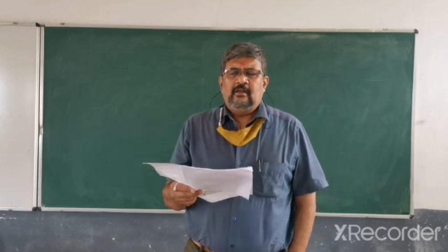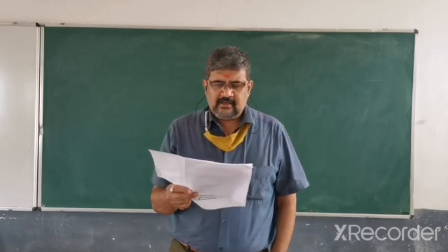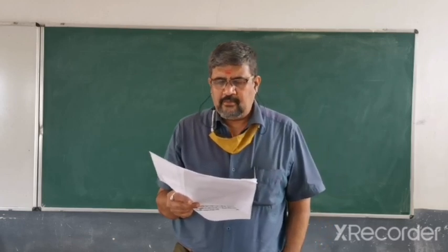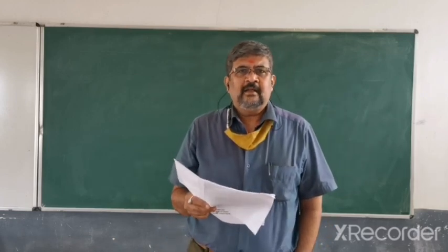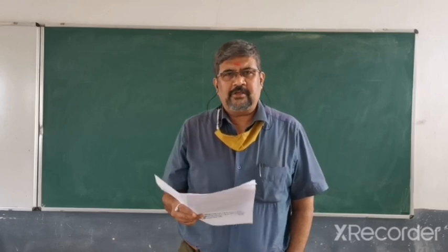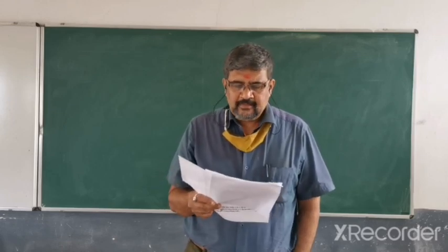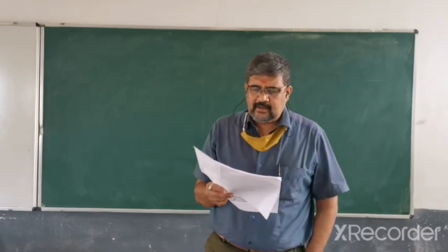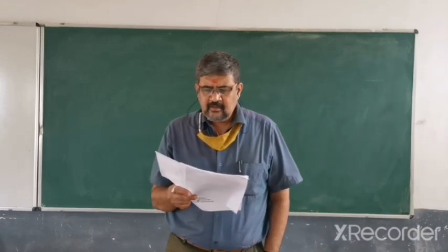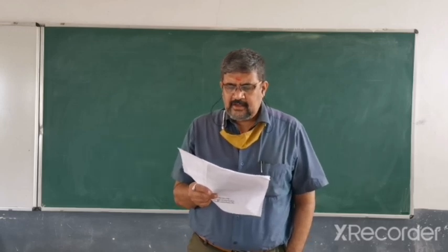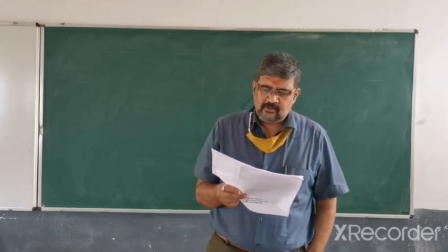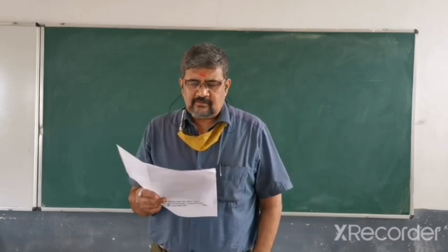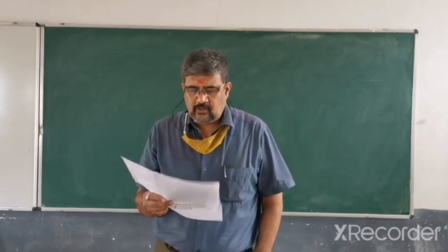And by looking at the values that are given, it is a single cylinder 4-stroke IC engine which has a bore of 180 mm. Bore is nothing but, as I said, the diameter of the cylinder or the diameter of the piston. We assume them to be the same. 180 mm is 0.18 meters. Similarly, 200 mm stroke length is 0.2 meters. And the rated speed, that is the crankshaft speed, is given as 300 rpm and so on.